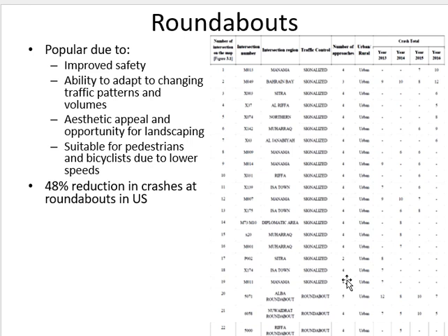In a roundabout, this issue takes care of itself. So you are on the roundabout, you will go in the same manner in high traffic condition and low traffic condition. The manner is, you have to wait for the other driver. If there is no other driver, you will enter. So for 2 hours, if there is no other driver, you will not stop for anyone unnecessarily, which can happen on a signal or a stop sign. So a roundabout is more efficient in this way.